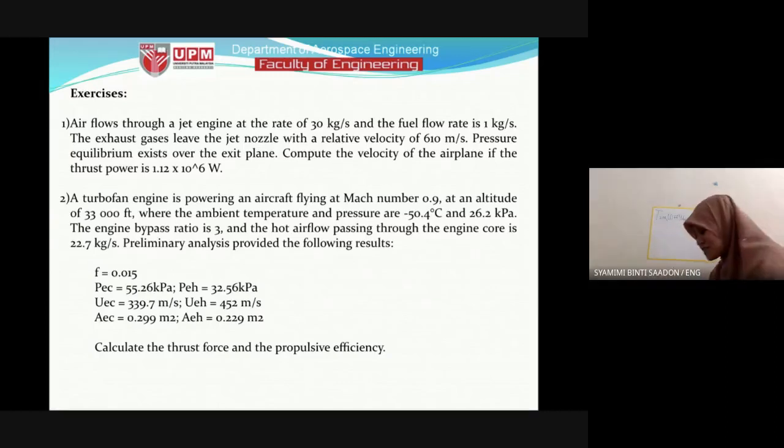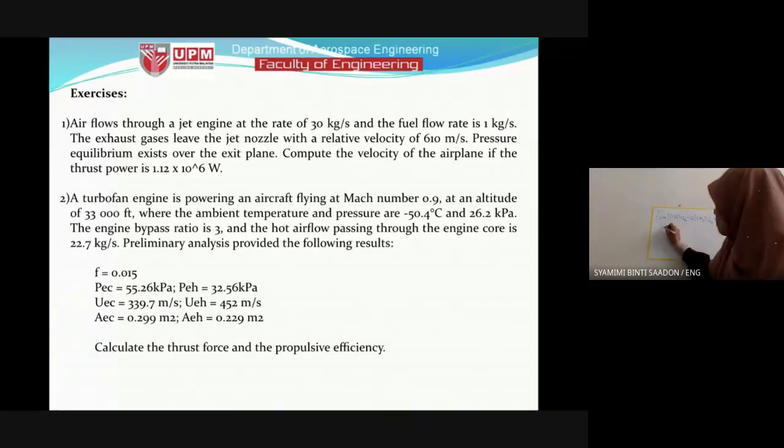Then the pressure thrust, so plus, that's why it's longer than turbojet. For turbofan, we have this equation, right? AE, the area, just now I forgot to add the area. The pressure thrust: AE multiplied with PE, exit pressure, minus PA, ambient. This is like the turbojet.